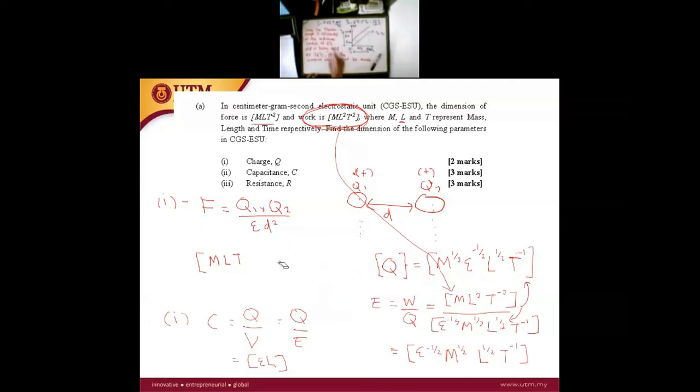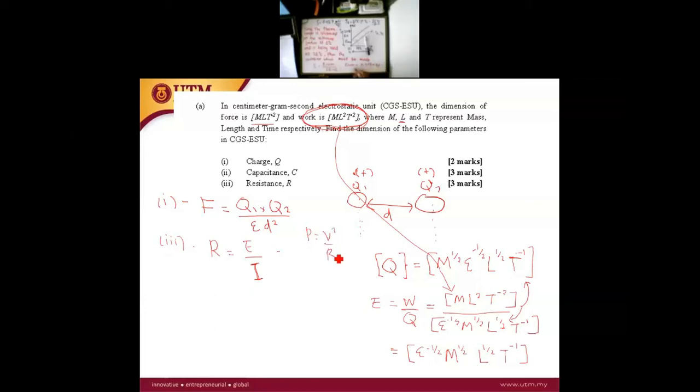So we can use this formula as equivalent. We take the E core divided by the temperature difference between 0 and 25. So E core is 25 minus 0. So we get that E core is equal to 0.057 multiplied by 25, so we get 1.293 millivolts. So that is the correction value that we must apply.